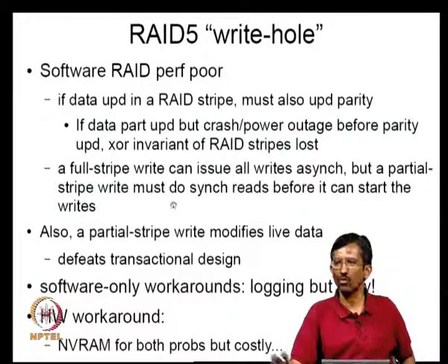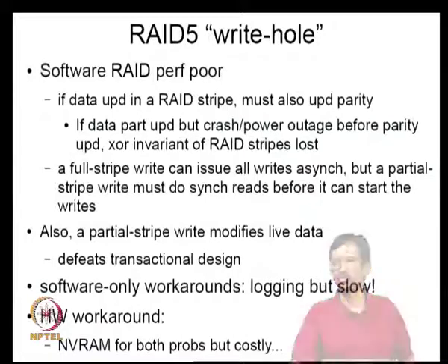So you might have to do some logging, etc. But once you have logging, that means it has to be somehow persistent. There are multiple ways of doing this. One is what is called NVRAM, that is battery backed memory, and essentially you keep track of this information, log it in NVRAM, and then because it is battery backed, in spite of whatever crash or power outage, you may be able to recover from it.